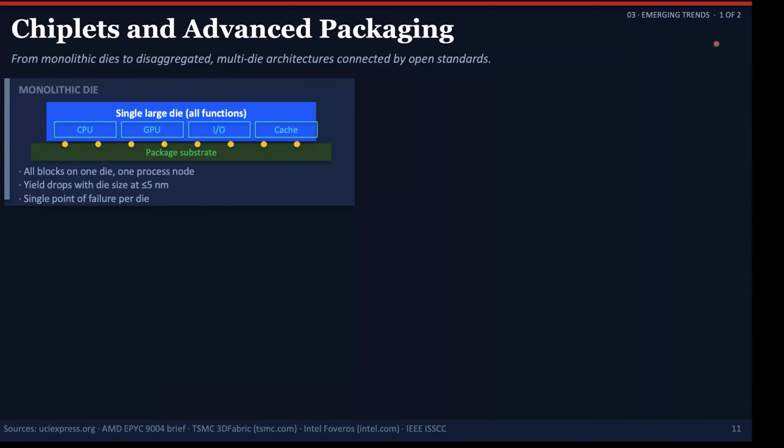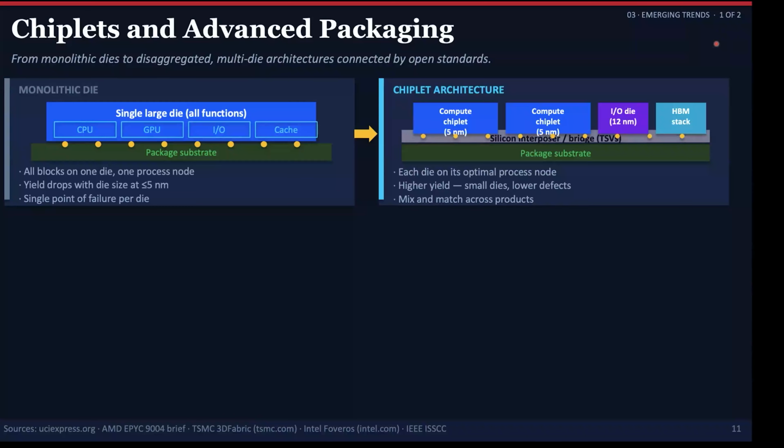On the right-hand side, you can see a chiplet architecture approach. Instead of putting everything on one die, the system is split into smaller dies or chiplets. Compute can use a more advanced node, while input-output can stay on a more mature and low-cost node.